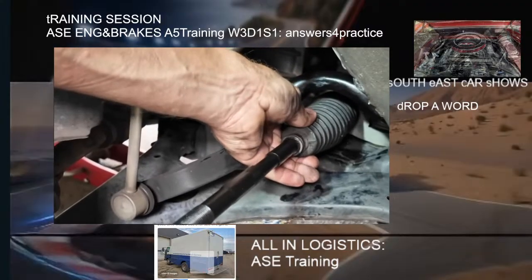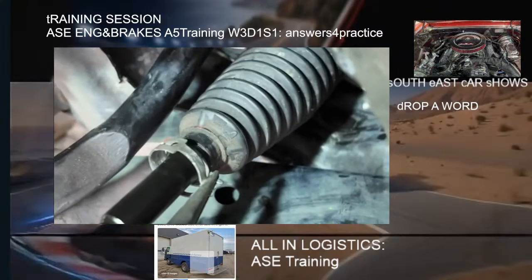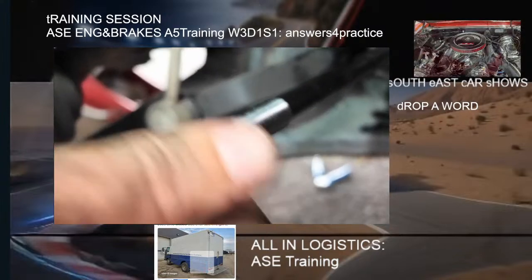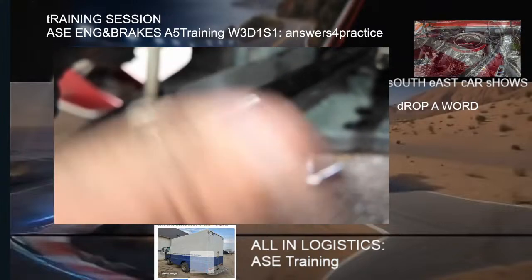Now I can slip this boot back to its outer groove and reinstall the clip. Now I'm going to put the locking bolt onto the inner tie rod, screw it all the way to the end.